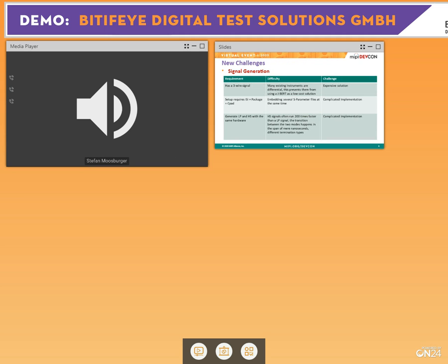To do this, we have to generate a 3-wire signal in MIPI C-PHY, which makes it a bit hard to use standard equipment like a bit error ratio tester, which just has digital signals. So we have to deal with an AWG, and we have to embed S-parameters in our signals, which is also not straightforward. We have to calculate our arbitrary signals. So first of all it has those 3 levels on the 3 wires, and on top of that, implement the channels with S-parameter simulations. And at the end, what is also very important, we have to switch back and forth between low power and high speed, which also makes it very tricky to really do that at speed.